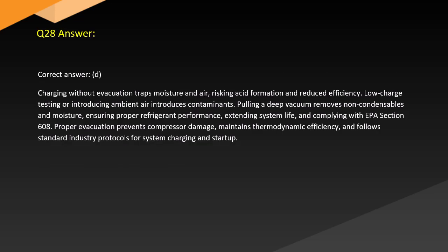Answer. Correct answer: D. Charging without evacuation traps moisture and air, risking acid formation and reduced efficiency. Low charge testing or introducing ambient air introduces contaminants. Pulling a deep vacuum removes non-condensables and moisture, ensuring proper refrigerant performance, extending system life, and complying with EPA Section 608. Proper evacuation prevents compressor damage, maintains thermodynamic efficiency, and follows standard industry protocols for system charging and startup.